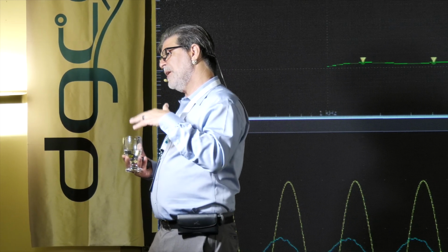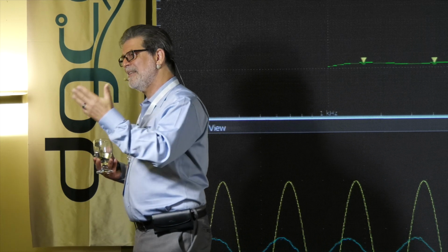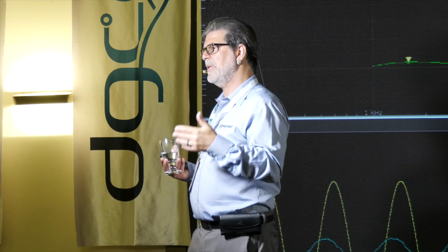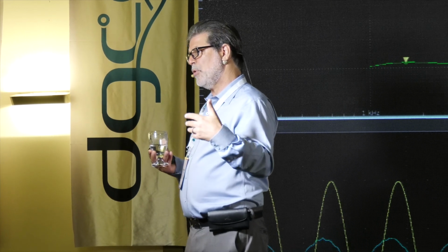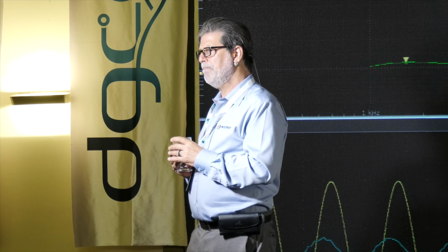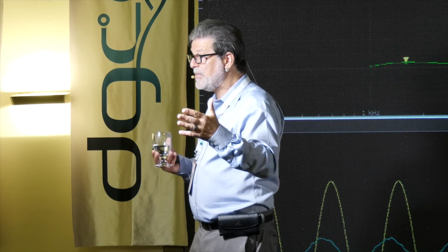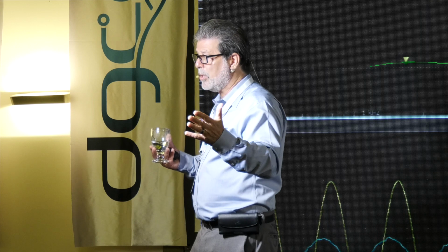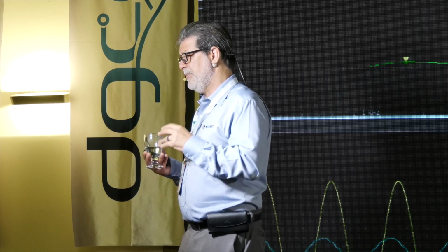I want to try to push that resistance up as high as I can because that's the damping of the network. If I have perfect regulation, that means there's no damping. And if I have no damping, it means it's going to be extremely difficult for us to try to meet a non-resonant flat impedance. It just doesn't work. And so very often we want to push the impedance up.